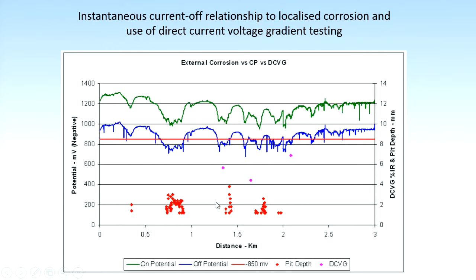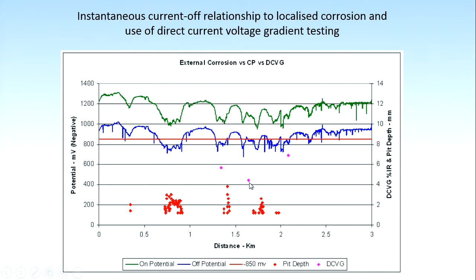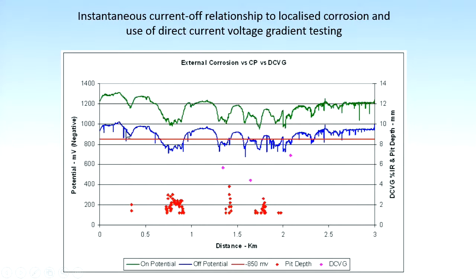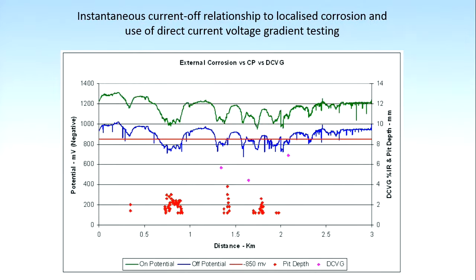On the other side of that handout, you've got this little table of data, which tells you something about the standards for current demand. That's the current demand through the pipe in milliamps per square metre for particular design lines. And again, there's a temperature factor. You should make an allowance of 25% for every 10 degrees rise in temperature above 30. And that makes sense because the kinetics of the reactions are faster, the diffusion is faster, and so on.